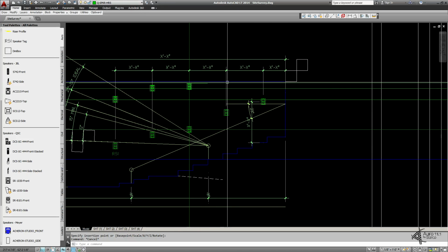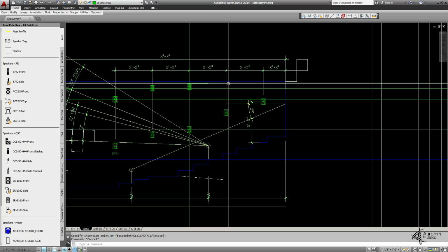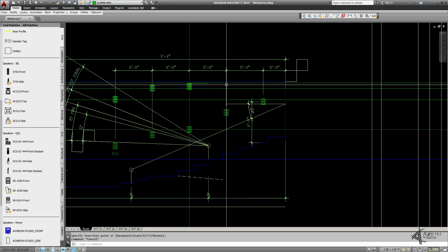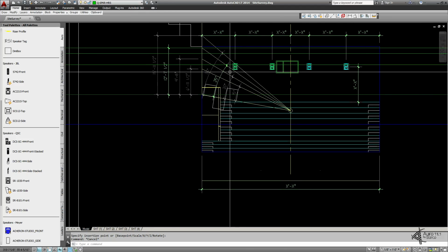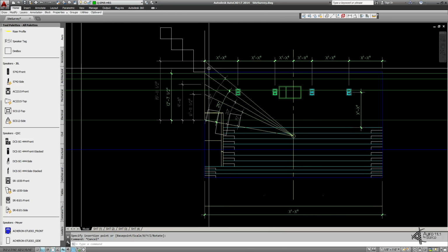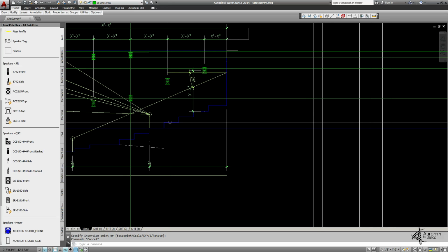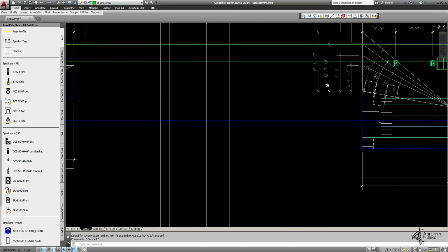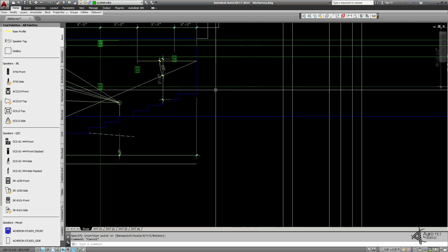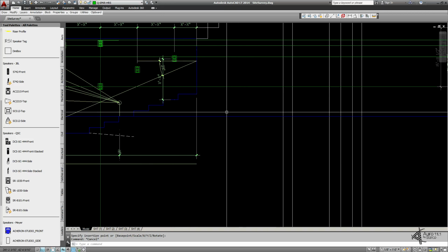You'll find that a lot of clients don't want to go into the expense of mounting speakers into the ceiling, and they'll get placed here above these, keeping that 6-inch minimum clearance there. And how you would determine where those speakers go into the ceiling is you would move your surround angle measurements up to the row that correlates to that surround. So we'll go ahead and do that here for this back surround.